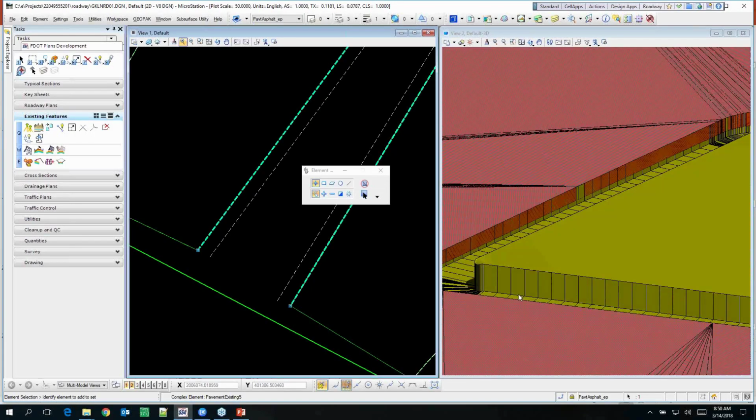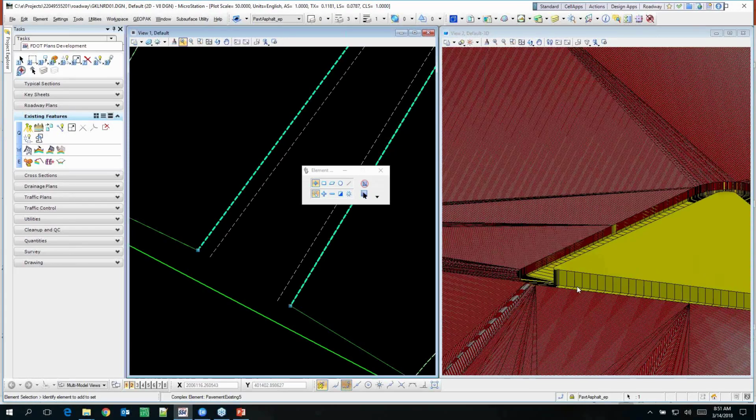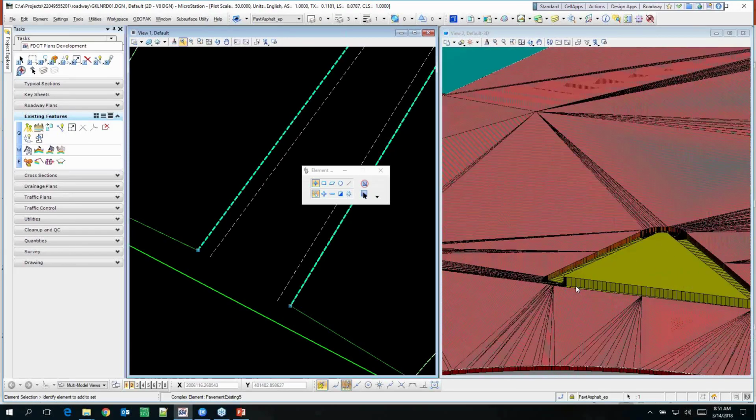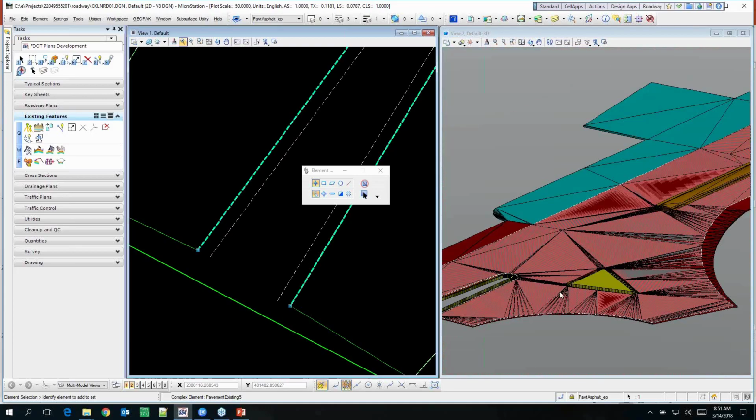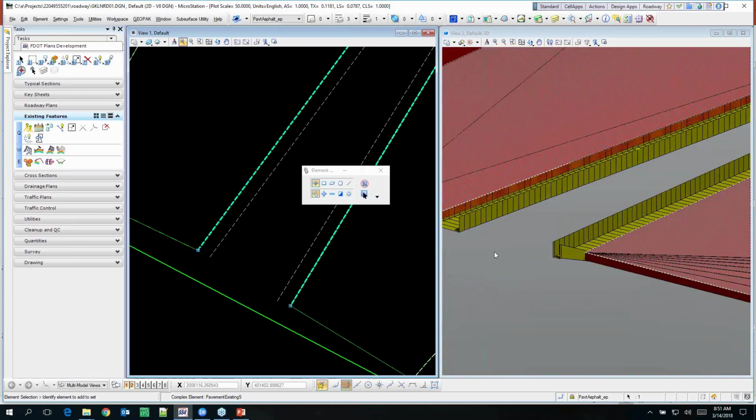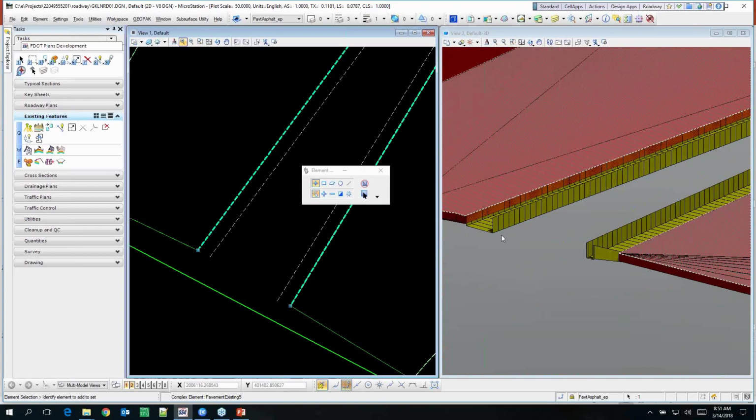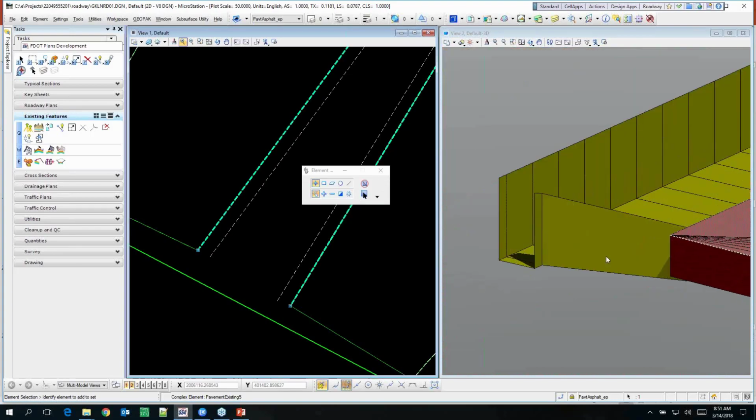You can only apply one depth to it, which is what we use a surface template for, anything that has a constant depth. So if you need multiple depths, what we came up with is using a linear template that has different depths for the front and the back. Instead of a constant depth, you apply what's called a linear template around an edge.